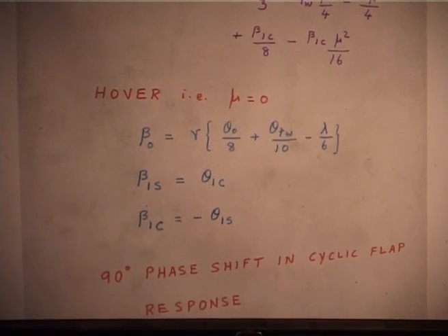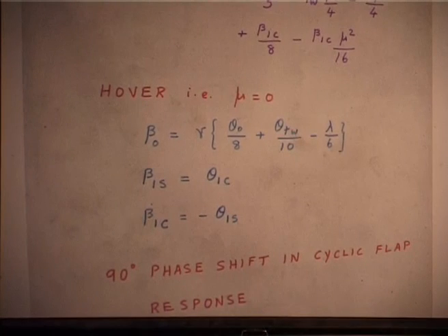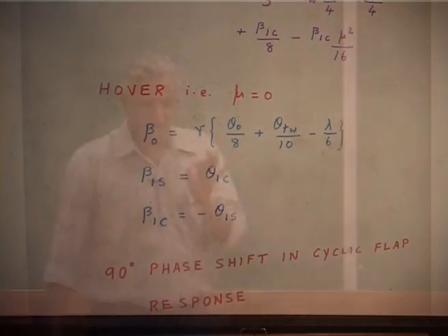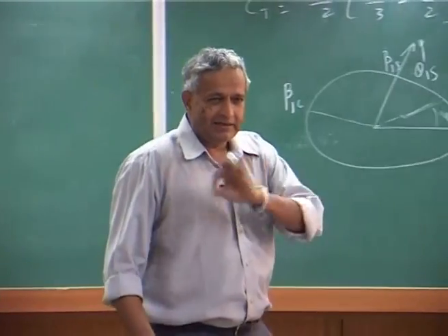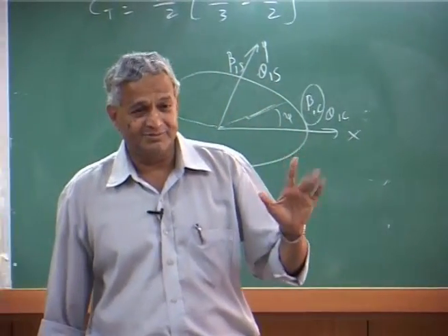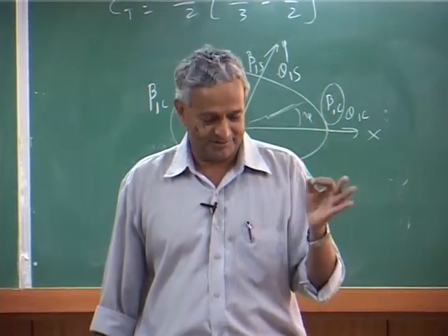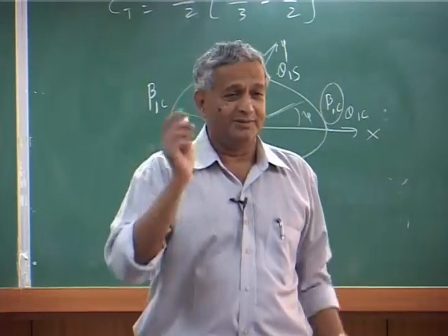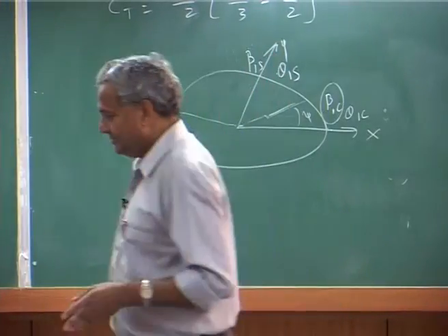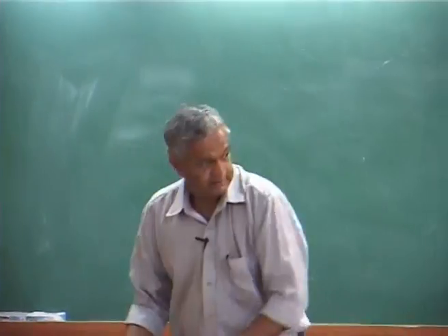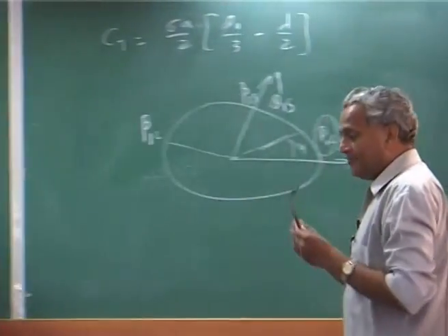Okay. It is a little interesting geometrical interpretation, I thought I will just show you. That is, all this for only centrally hinged, because when you say centrally hinged, immediately you must know flap frequency is 1 per rev. That means, flap natural frequency is just the rotor RPM itself, nothing else. Okay. Now, let us look at because we defined earlier